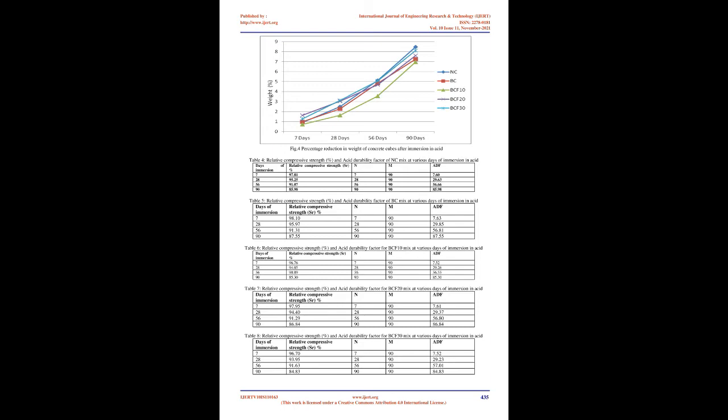3.4 Water. Locally available potable water conforming to IS 456 is used. 3.5 Fly ash. Fly ash of class F with 2.23 specific gravity is used. 3.6 Microorganisms. Sporosarcina pasteurii of 1x10^7 cells/ml concentration, a soil bacterium which is cultured and grown at the Laboratory of Biotechnology Department, CBIT, is used. 3.7 Grade designation, M-20 grade concrete.